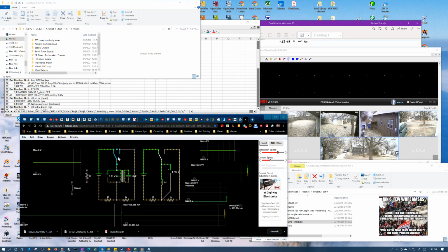Okay, now let's give it a whack, charge it up. You can see the capacitor went up to 8 volts from that whack, and you can see the oscillation in the current too, and even on the voltage there was a little bit of a hit. But overall, our max current is going to be about 1/2 amp with a 10 ohm resistor there. This thing is almost charged up fully now.